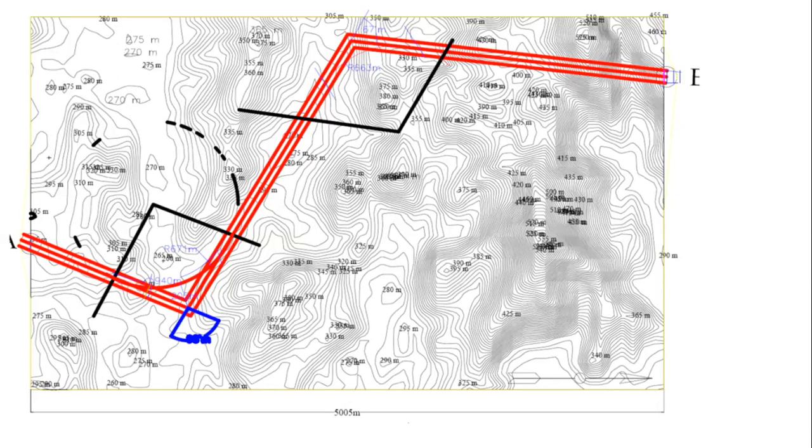But mind it, sometimes you have an AutoCAD drawing and some of the layers may be off. So what I am saying is, when you are looking at this topographic map, please check that the layers that have development marks like buildings, mosques, roads are not switched off, because all these developed features are drawn on different layers.